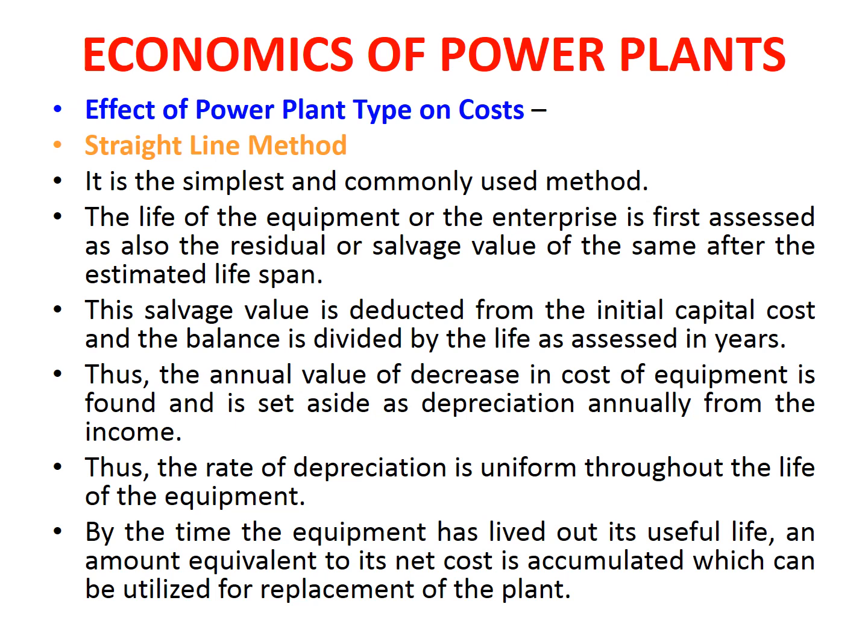So in this method, the first thing done is that the life is assessed. That is, the life of any equipment or power plant is first assessed, but at the same time it is compared with the actual value or the residual value when the estimated lifespan is there. Means, when the machine is purchased or when a power plant is designed, as we have seen, if a power plant is designed for 50 years but the actual life is expected up to 40 years only, then this salvage value is deducted from the initial capital cost and the balance is divided by the life as assessed